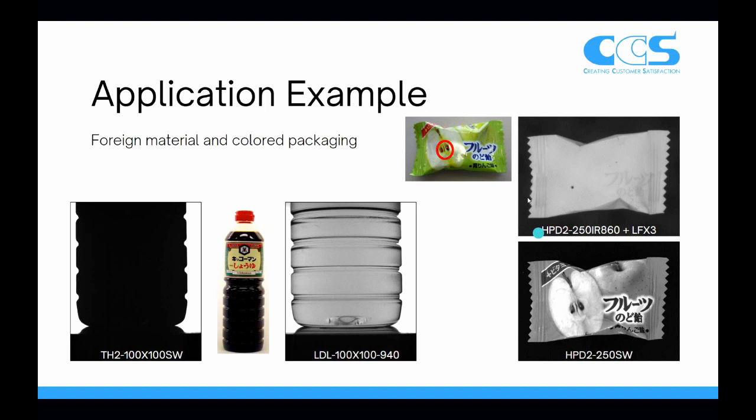On the same side, we're using it to remove print. There's a tiny pinhole that in visible light you wouldn't be able to detect or distinguish from the print on the package. But with IR light, that wavelength passes through the print unchanged, but reflects off of the plastic material. So it's essentially removing the print, but still showing the pinhole and the plastic packaging.